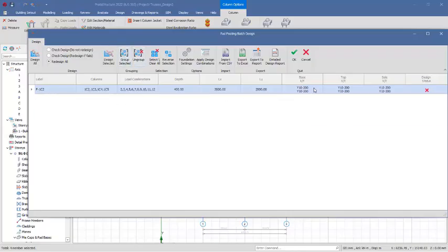To consider a group design, you have to select the number of columns you need to add a foundation to, just like this. Right click on it and then click on insert pad footings. Once you click on insert pad footings, it is going to come up with a dialog just like this. Here you can group all of these as one. If you want to group, you need to select redesign all first, select the first one, then hold the shift key and select the last one, so that you get all selected just like this.